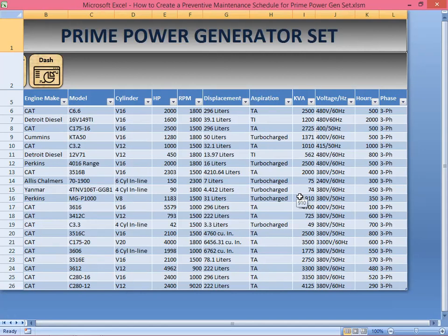The purpose is to increase the density of the air going into the pistons, into the combustion chamber, for efficiency in combustion, to get more power and generate more horsepower.